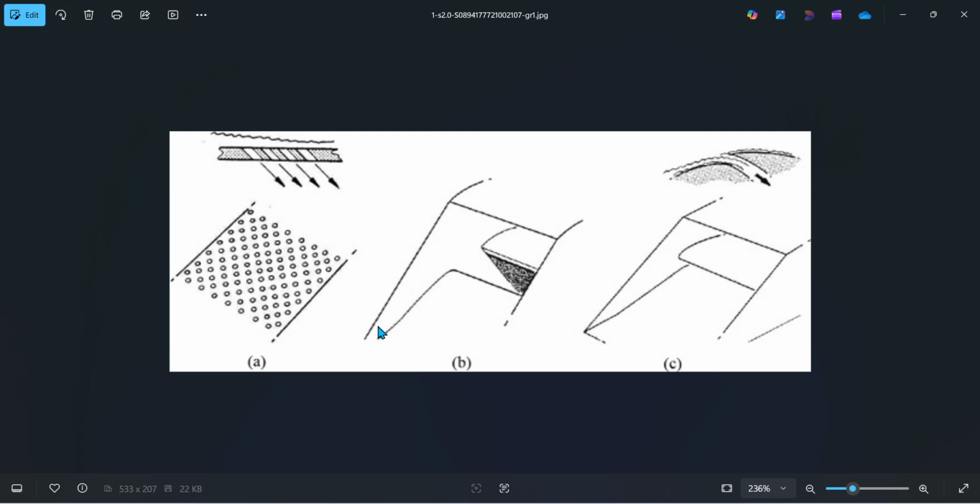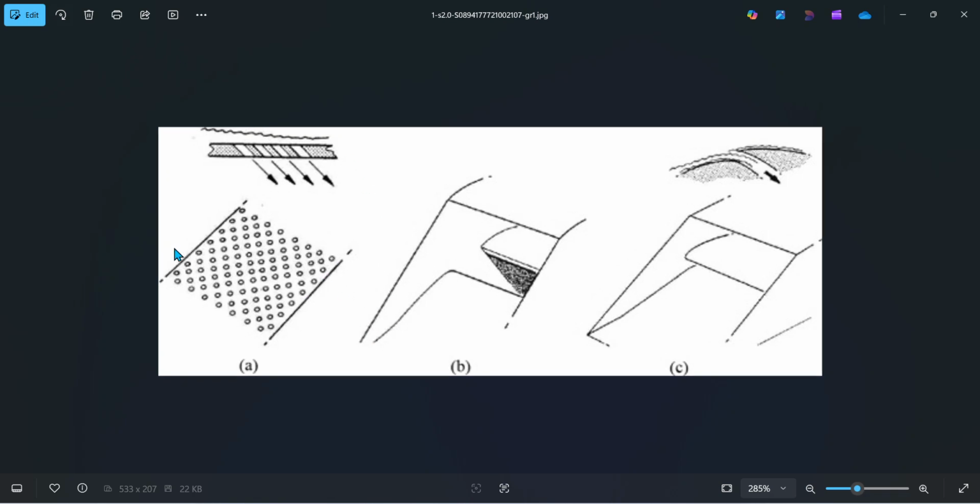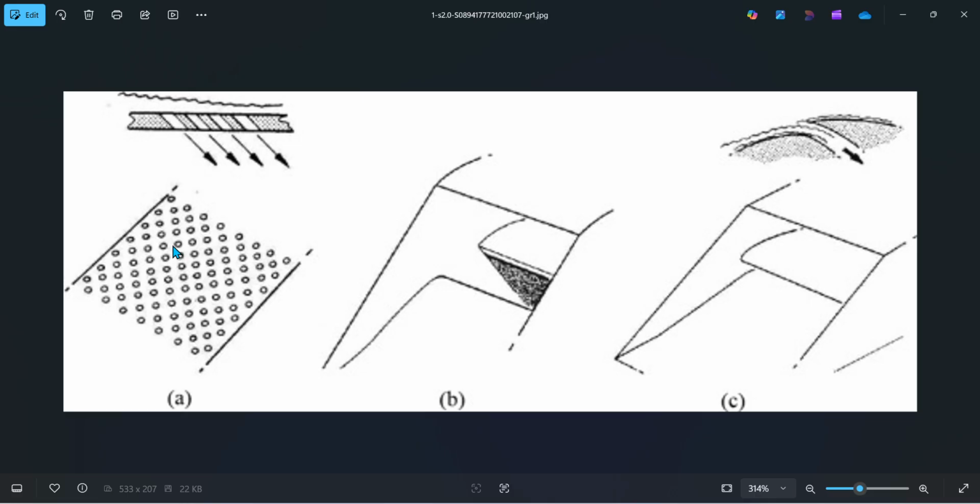In the last session, we saw the mixed compression supersonic intake system when we are applying bleeding. In the last video, whatever we saw is called porous bleed, because the hole size is very small. When the hole size is very small, we call it a porous bleed. Now we can increase the number of pores, that is holes. One, two, three, four, five.